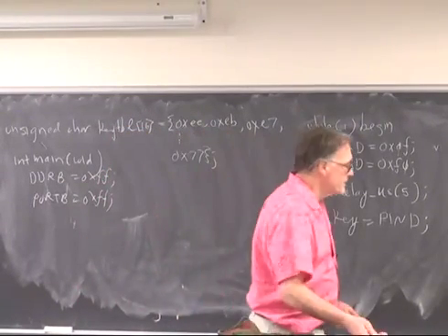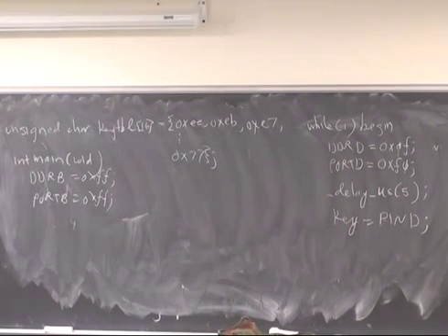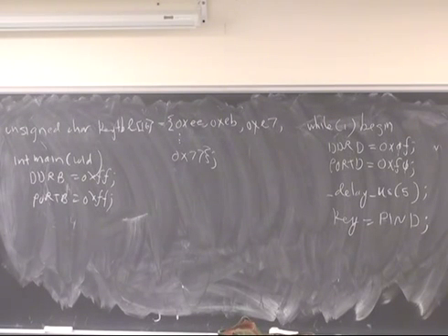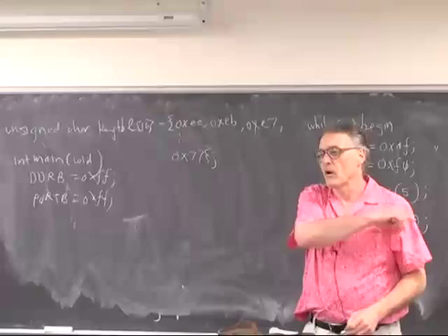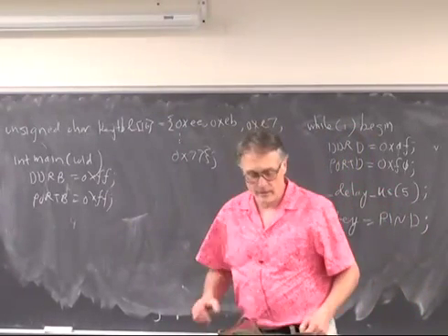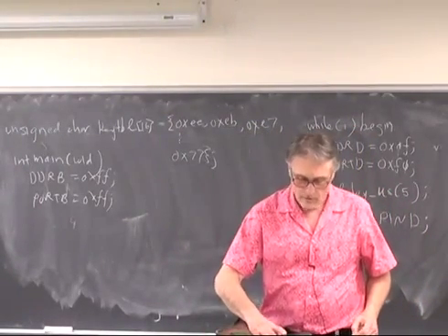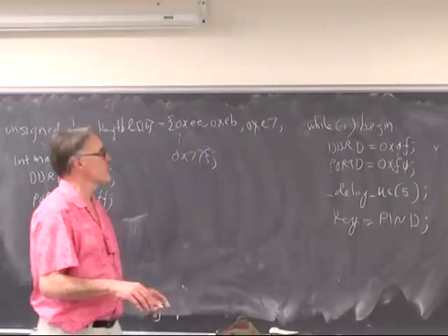The first time I wrote this code was at home using a cycle accurate simulator. And I wrote the code without the delay, and it worked beautifully. So on Monday I came into the lab and put it on the microcontroller, and it totally did not work. So the simulator always lies. You should always remember that. That's the first rule. You write it on your forehead. Simulator is always wrong.